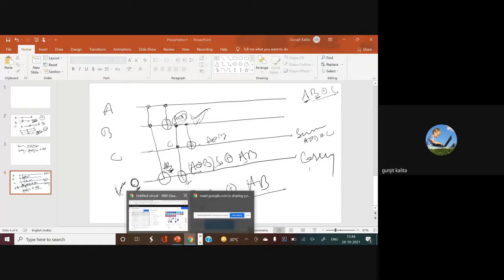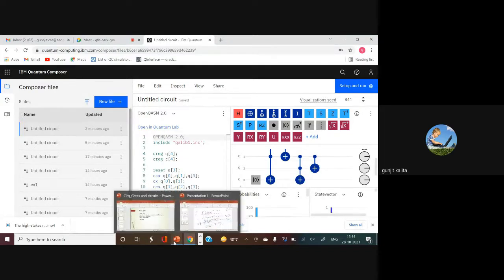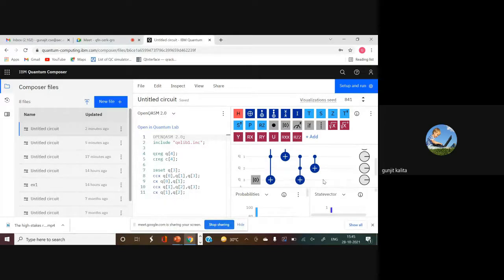So now if you see, the circuit becomes like this. Once you make this circuit, whatever we have done is written over here. Now we need to take the measurement of this. The circuit is designed. It's a full adder circuit now. We will measure what we need. The other measurements we don't need, so they are unused, so they are garbage. Now what we need, if you notice, is the sum and carry part. Carry is in Q3, and sum is available in Q2. So these two we require. That's why our measurement will be from Q2 and Q3 only.